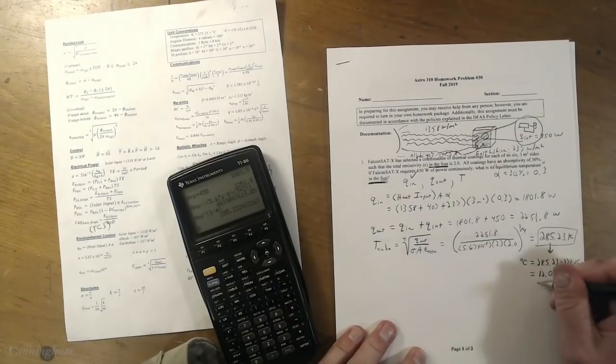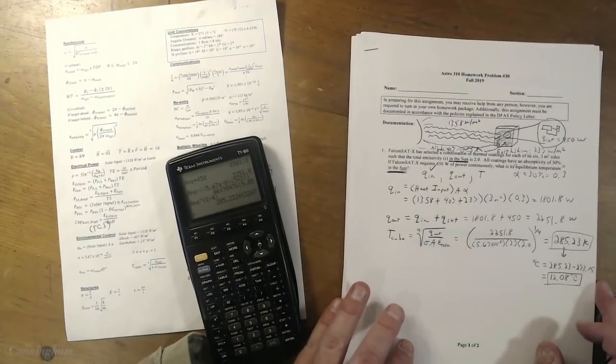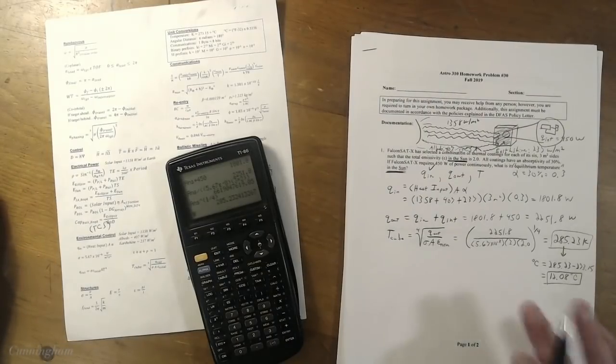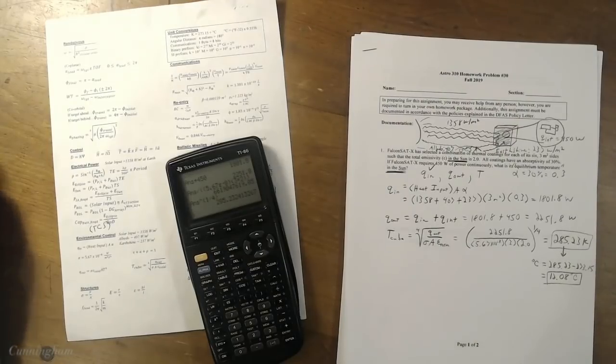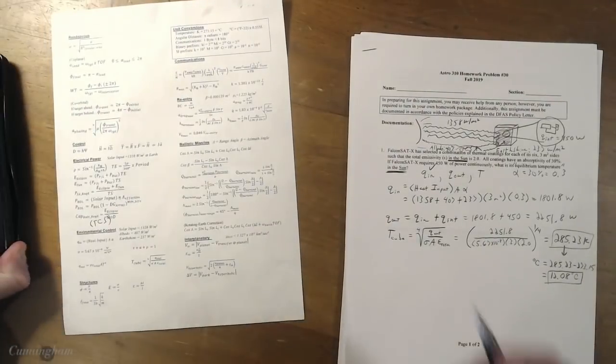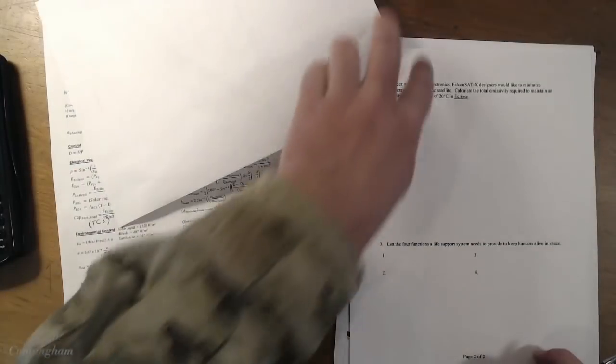So anyway, this was correct. You could stop there. This just makes a little more sense. So anyway, that temperature, even in the sun, because FalconSat is emissive enough, it actually stabilizes at a pretty sane temperature. Like you could survive at 12 degrees Celsius. You might not be comfortable, but you probably wouldn't die. So anyway. Great, so that's starting off with Q in, Q out, going to temperature. Another way you might see this